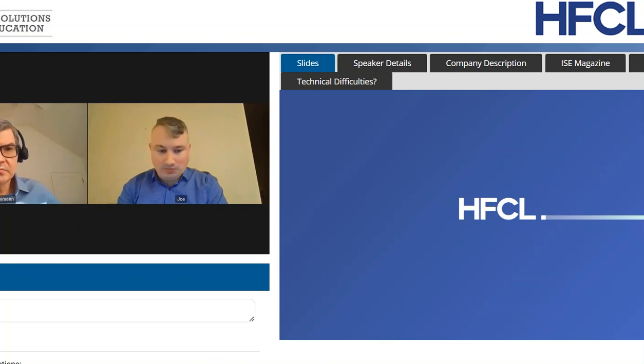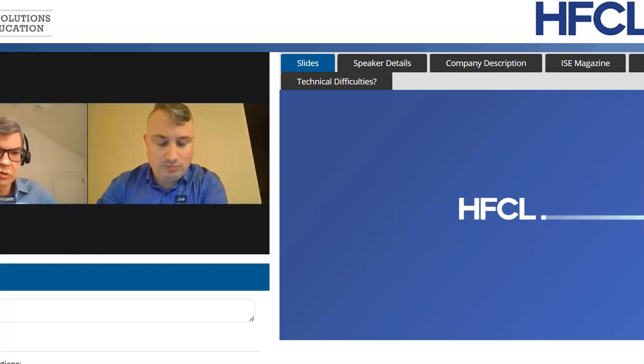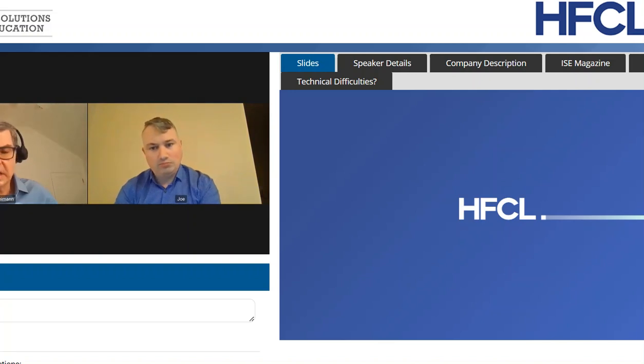Yeah, we can do a number of things for that application. It's actually pretty common in Europe, and right now we have a much bigger presence in Europe than we do in the USA, and I do work with the European market. So we can offer, for regulatory reasons, all the drop cables in the UK are 4 fibers. And so for an open access network, we could do a drop solution where we put multiple cordages inside, essentially a breakout style cable. We can provision extra fibers for open access, or we can do things like breakout cables if you want multiple cables to reach multiple premises in a garden style.